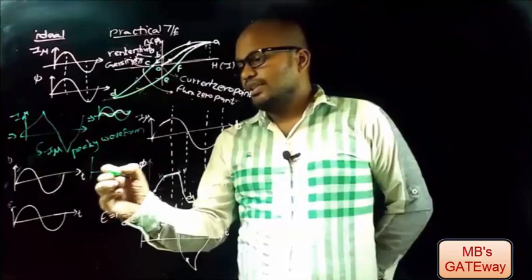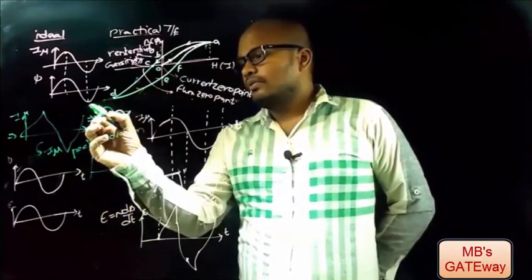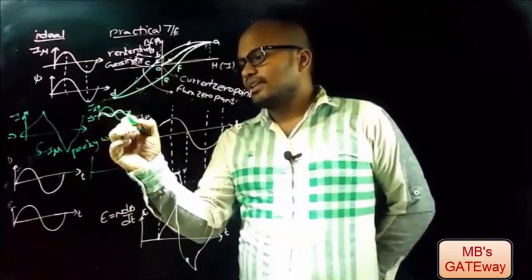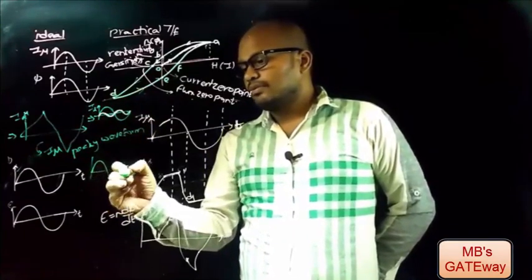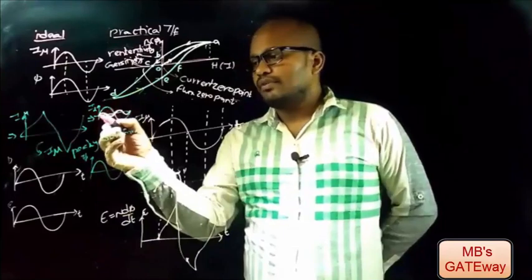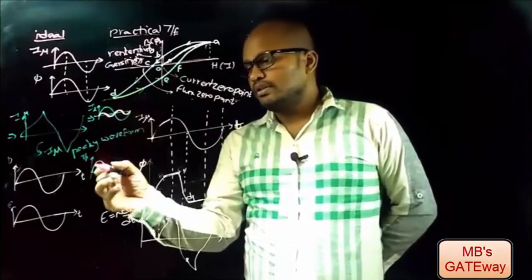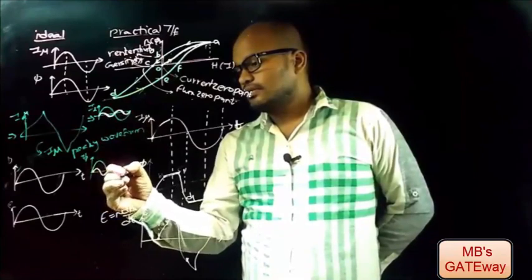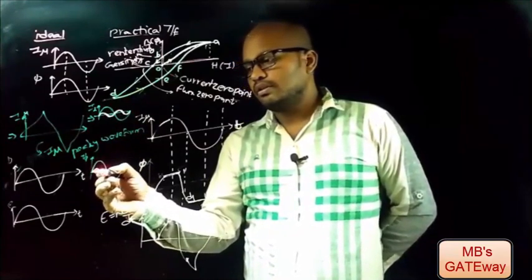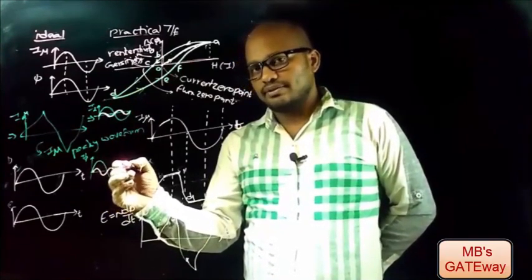So actually in transformer, for this magnetizing current there must be flux of sinusoidal nature, and for this third order harmonic current there must be third order flux.